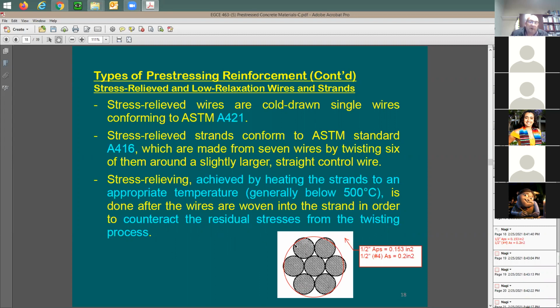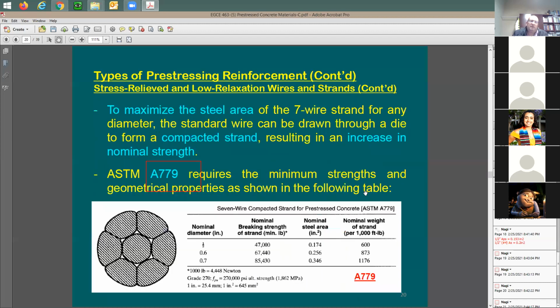And if you try to do this epoxy coat after you twist them, what's going to happen to this area here? You cannot really cover it. So it's going to be a tough process. So what do you do? Usually it comes covered in grease. Certain rebars and tendons or strands come with no grease, but in this case, you're going to be grouting it after the fact. After you do the pre-stressing, you grout it. I guess we have seen some video clips on this, right? You grout after you do the post-tension, you grout the space between the strand and the conduit.